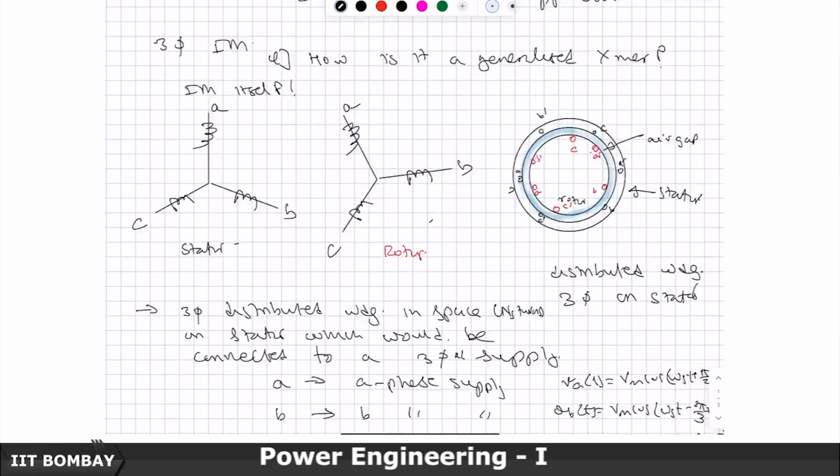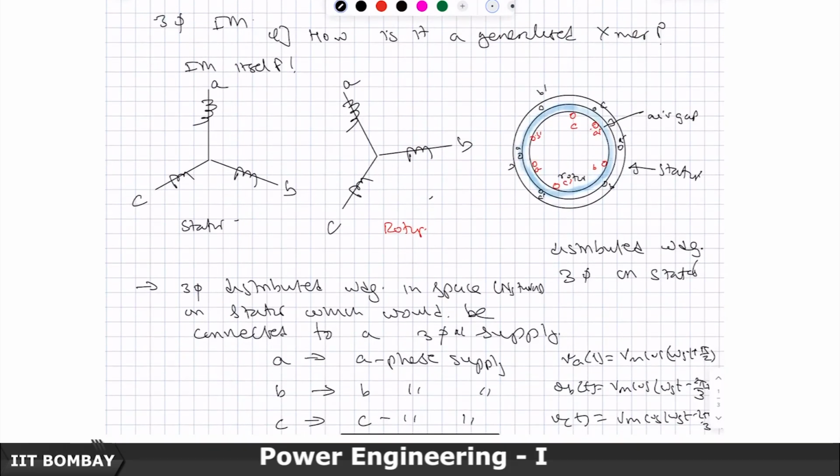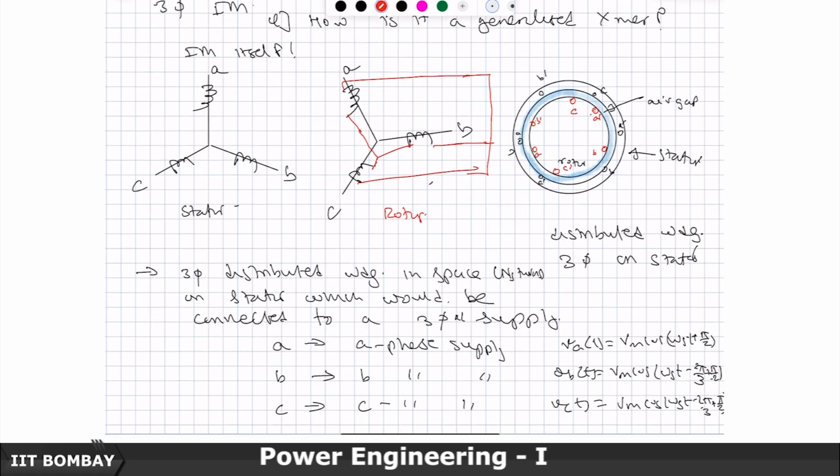So, what I did basically is these 3-phase windings here on the rotor. This is connected to this, I said star connection. These terminals are what are available outside, and I just short circuited them. So, this short circuited whole assembly has a degree of freedom to rotate, and right now you do not have any control on that.